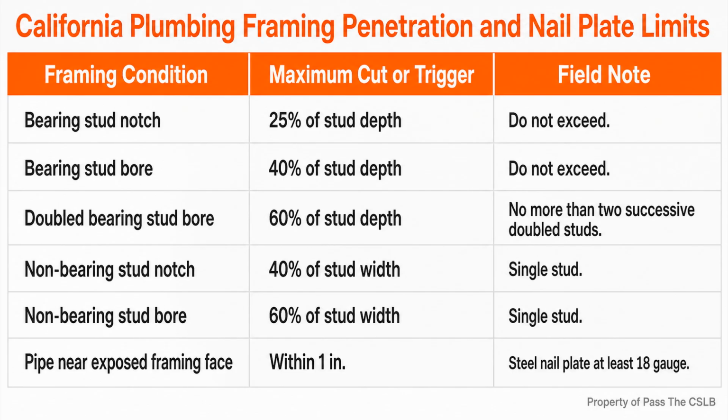Compressed air stores energy. If a plastic fitting or solvent-welded joint fails while pressurized with air, the expanding gas can release that energy suddenly and throw broken material outward. Water does not store energy in the same way. A failed water test creates leakage and cleanup, but it does not create the same pressurized gas release.